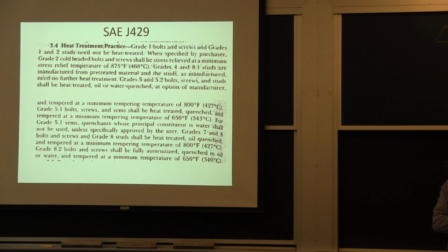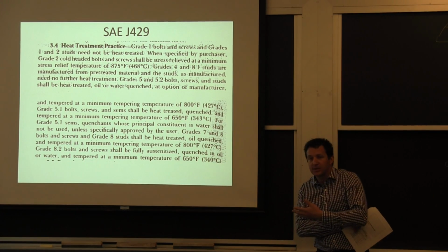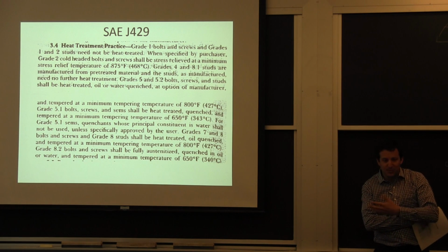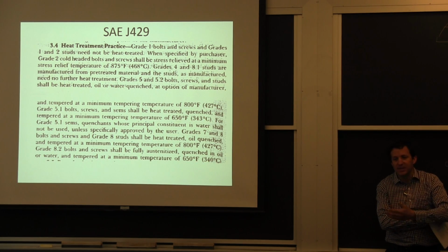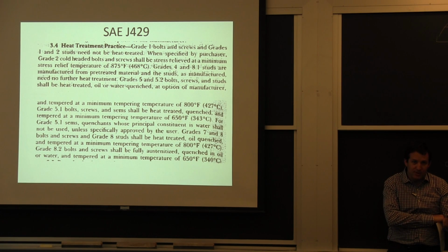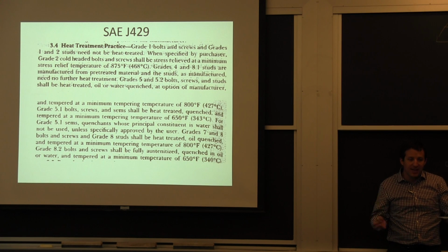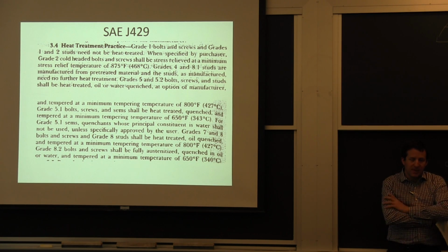One of the reasons is you get the best surface properties. One of the consequences is that every once in a while someone buys a bar that's been quenched and tempered to the same requirement and machines threads on it, and you don't get the same properties as if you did it the other way around, getting to shape and then doing the heat treatment.